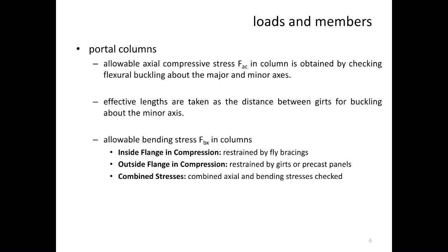So that's a buckling failure when it fails that way. So that becomes a criteria you need to check in the minor and major axis. Okay, when you have the girts, and as well for the rafter, when you have the purlins. So as I explained yesterday, you have a series of girts. So assuming each of these are the girt points, you have a series of girts going this way.